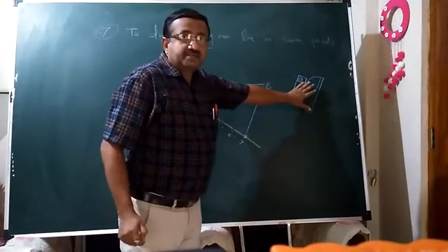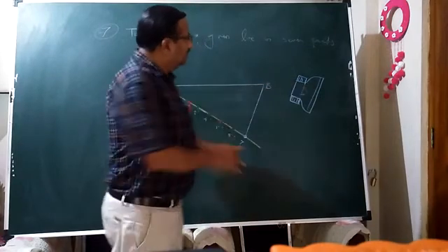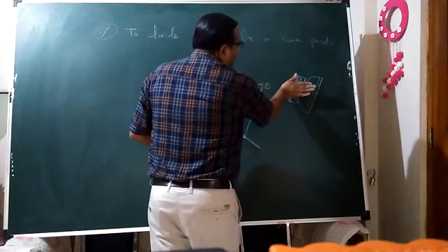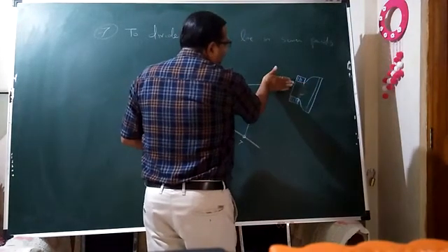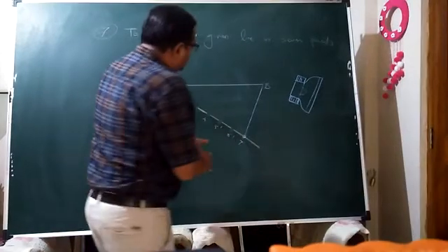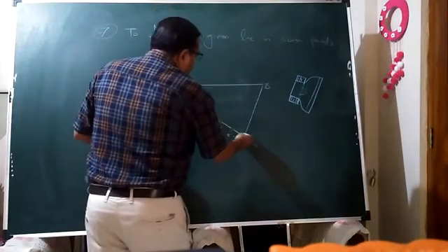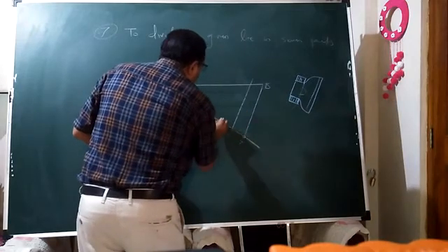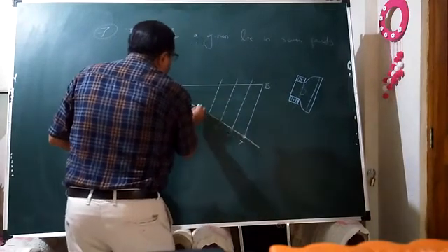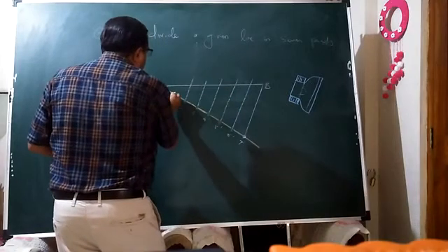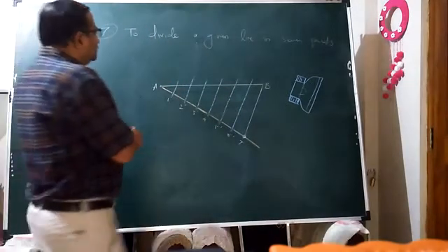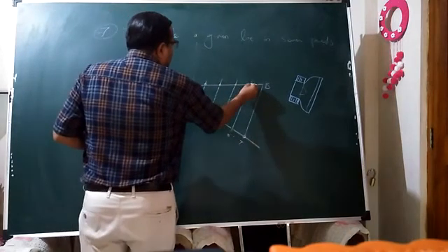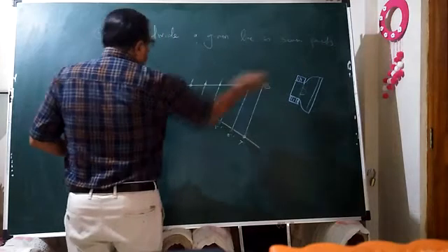Okay, what is its function? With roll and draw, just put stress over this roll, pick the blade, make it roll, apply the brake, get the line. So in this way, parallel to this 7 dash B line, you have to stretch the segments by using roll and draw in this way. So ultimately, these 7 equal segments we have got of this line AB.